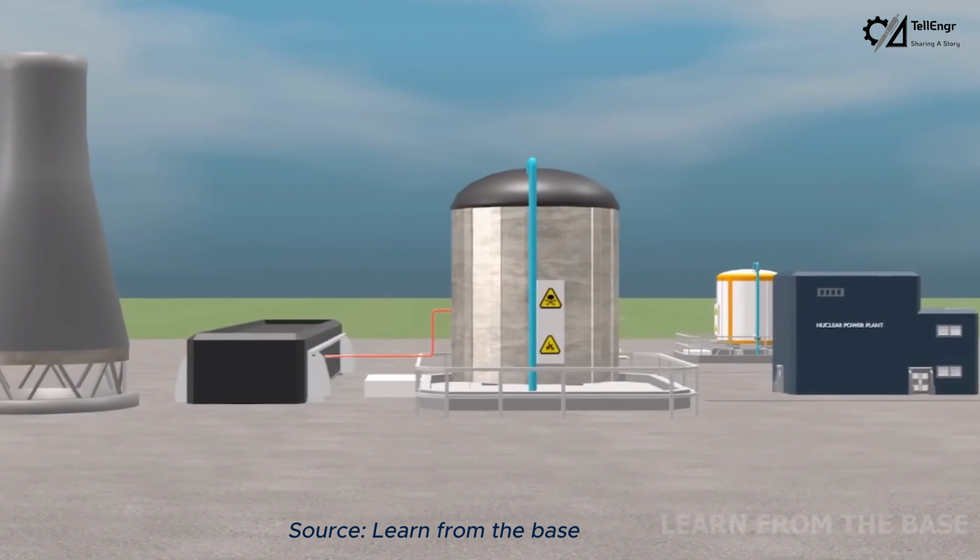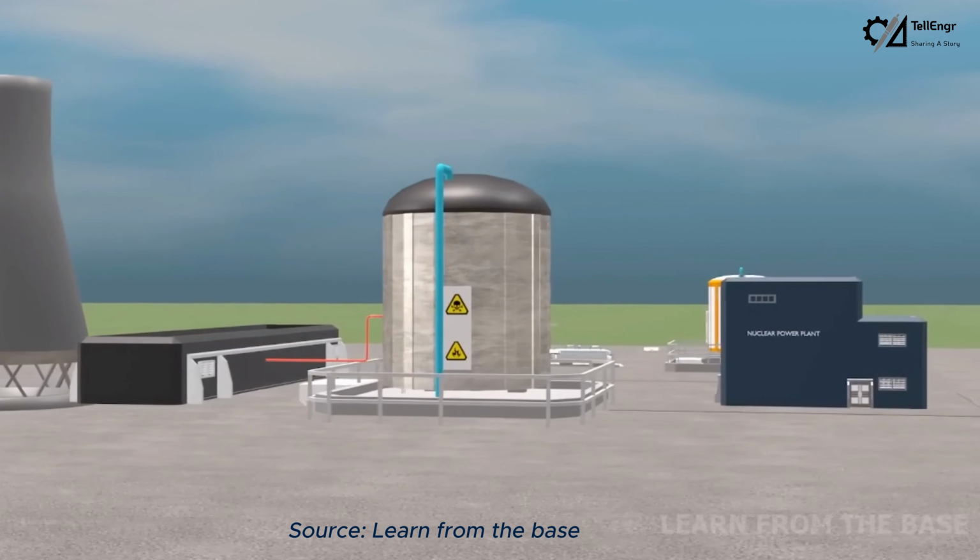These flow patterns and their associated flow maps hold significant importance in industrial applications. They aid in predicting flow rates, pressure drops, and behaviors in various scenarios. One prominent application of these maps lies in nuclear reactor design, especially in scenarios like loss of coolant accidents. Engineers use these maps to analyze the behavior of liquid and vapor phases within pipes during heat transfer processes.